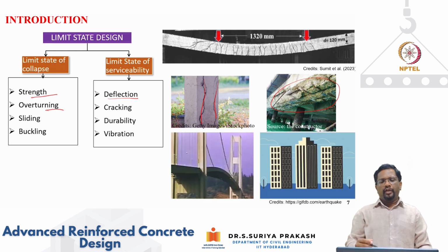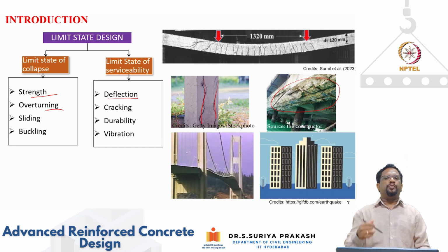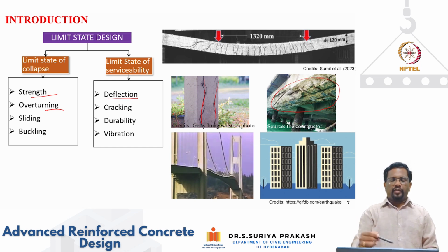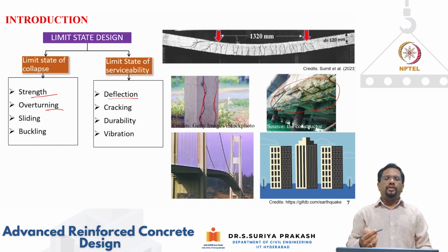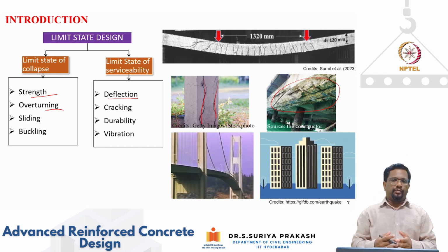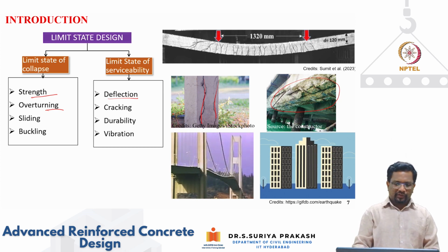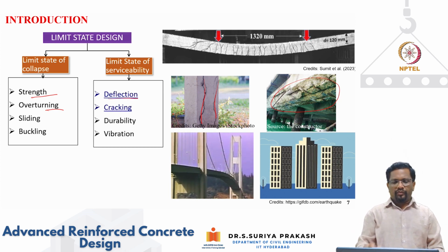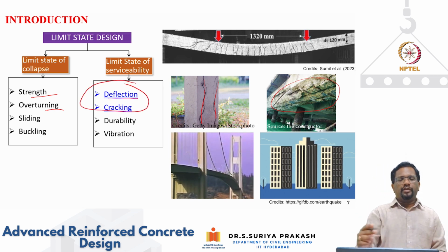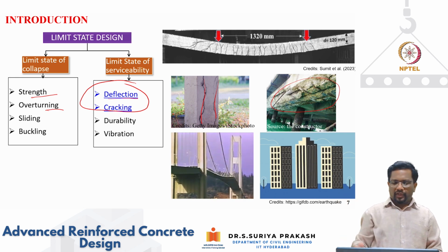And vibrations, again, in long span bridges, you must have seen, if your dimensions and arrangements are not proper, like the one that we are seeing in this image, you can see that long span structures are more prone to vibration because they're very slender. And if you're not careful, vibration of the structural system may affect the performance and usability of the particular structure. So we need to check. So in this, we are going to focus mainly on deflection and cracking, and durability we have already discussed. Vibration is a topic in itself, so we are not going to cover that.